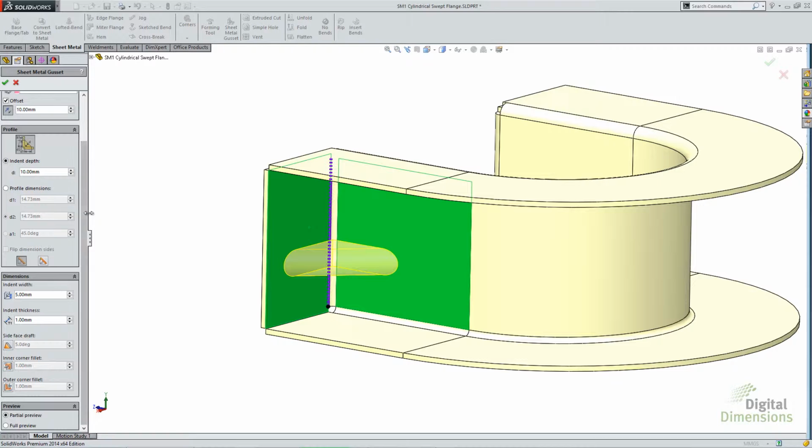The next section is where you really define the profile. So if I just want a uniform size in both directions, on both faces, this direction and this direction along the face, I can just do a depth of 10, whatever that is, and I'll just jump it up, and you'll see obviously I have to pick something that fits within the parameters, but you can see that just adjusting it will change that size. This little picture is kind of handy. It shows you where the D1 and D2 is and the angle and the depth.